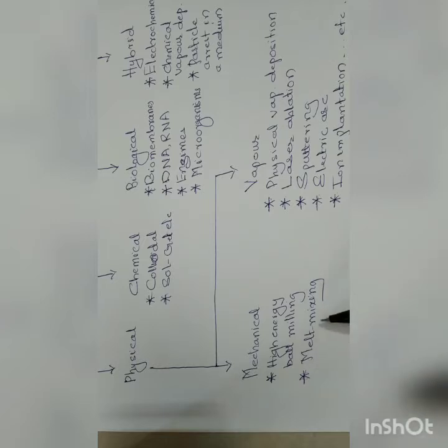And also there is a technique within this that is called melt mixing. You melt another material along with the material which you want to have in a nanoform. Its precursor you mix, and in the process of mixing and heating you try to convert the material into nano size, which is well dispersed in the medium.